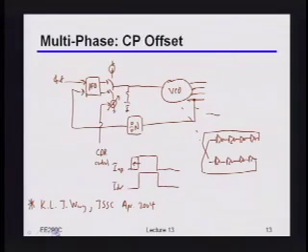So what's kind of painful about doing that in this particular design? Why does that kind of suck if you want to have the thing wrap? It's analog. It is analog, but let's be more specific: what would you have to do when the thing wrapped? Take your current from high to low? Yeah, exactly. What you'd have to do is figure out the magic current level that, at the high level, if I flipped it back to the low level, would give you exactly 360 degrees of phase shift, right?